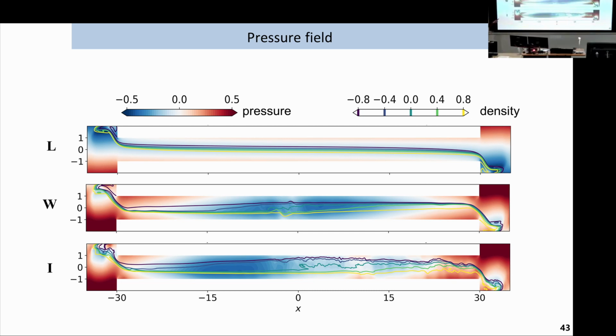On the other hand, if you go to the wave case, you see that's no longer true. So the pressure is high here, gets low there, but then it gets high again. Okay? So the pressure gradient here is prograde, it pushes the way you want to go, but when it gets to here, it starts to decelerate the flow. It's retrograde. So now, the system is behaving quite differently. Whereas the hydraulic control in the laminar case is associated with the flow over the end of the reservoir, because that's what you normally expect to flow over a weir, is your hydraulic control, here, the hydraulic control is caused by the pressure minimum in the middle of the duct.